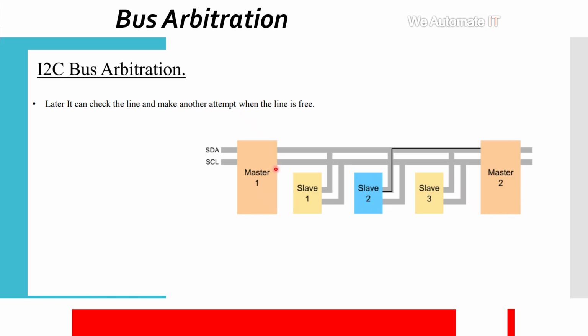So as I already discussed with you, what is I2C? It is the inter-integrated circuit, used for communicating between devices over two wires. They are bidirectional. It has 7-bit and 10-bit addresses. It is used only for small-distance communication, and with 7-bit addressing it can connect to 128 devices, and with 10-bit addressing it is used for a larger number of devices.